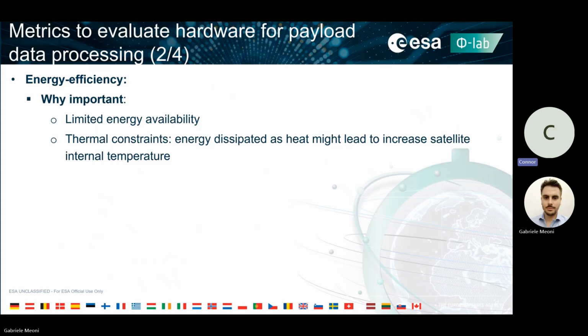You also have thermal constraints. It's not only a matter of energy: when you produce power, you need to dissipate it. And very different from what people believe, dissipating heat in space is not very easy. So there's actually a problem. If your power consumption is too high, then you need a very efficient way to dissipate heat.